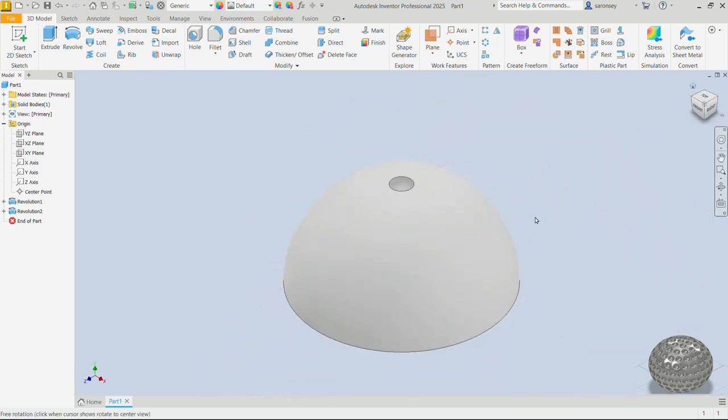Okay, next we want to create the next set of dimples. And so the next one is going to be at an angle of 15 degrees to this first one, and that is going to be circular patterned around, so we get 6 instances. The next dimple again is going to be at an angle of 30 degrees to the first one, and would also circular pattern that. I think about 12 of them around that circular axis.